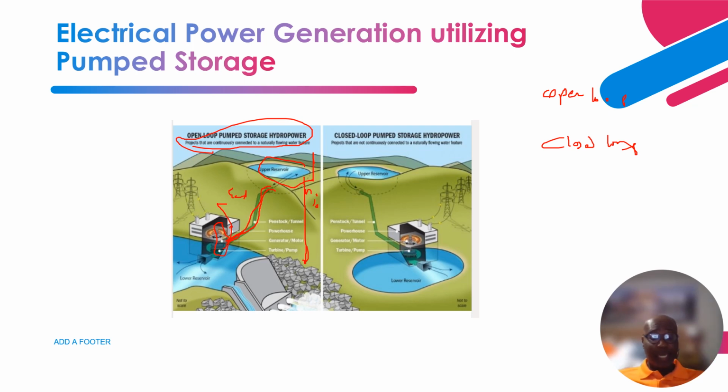As the rotor of the generator rotates, that magnetic field cuts the stator winding, which is a conductor, and it induces voltage. It keeps building that voltage until the required voltage is reached, let's say 13.8 kV or 21.3 kV. Those are typical terminal voltages for hydro generators. Once the water passes through the turbine, it comes into a lower reservoir.